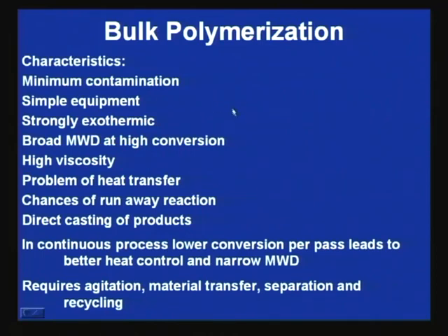I said this problem of heat transfer. So, I showed this schematic of that polymerization reactor, where a huge stirrer is used. So, with the progress of growth, viscosity becomes high and heat transfer becomes a problem, and that may lead to local hotspot generation, and there unwanted side reactions may occur, leading to polymer branch formation.